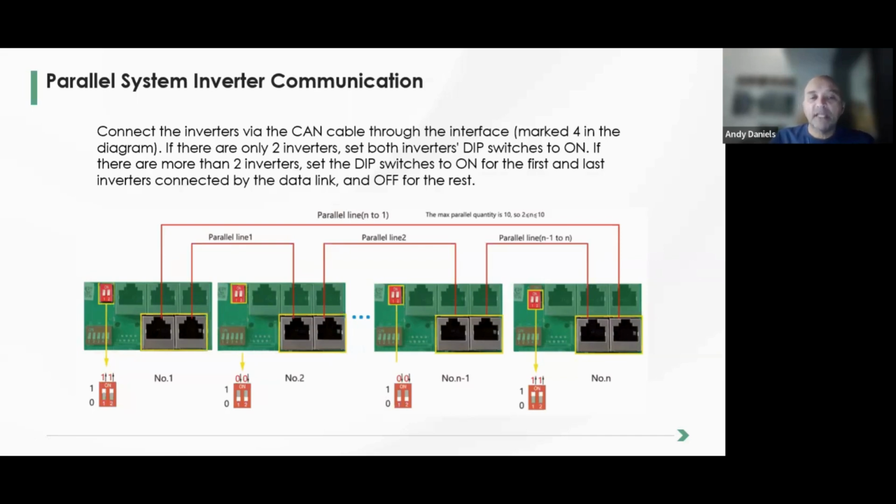Number one, make sure that we have guys that do beautiful trunking below the inverters, and once you're running all your communication cables in there, you kind of don't know which end is which. So it's handy to have a cable tester to send a signal down the line to see which one is which, because it's quite important that you follow this sequence, right? So that you go from this one to this one and then jump, and like that. You've got to do that.